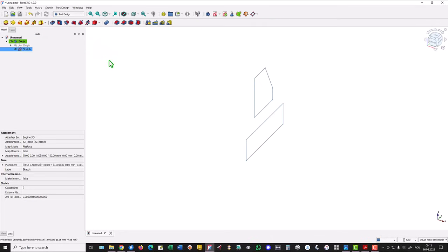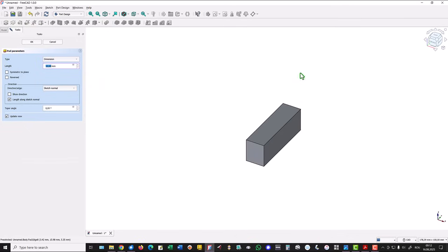If we apply pad or extrude, FreeCAD selects one of the two closed contours to create only one object. In Inventor you can make the same sketch and you'll receive both objects.